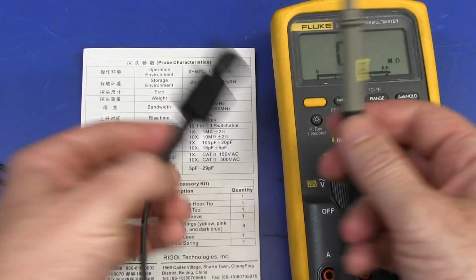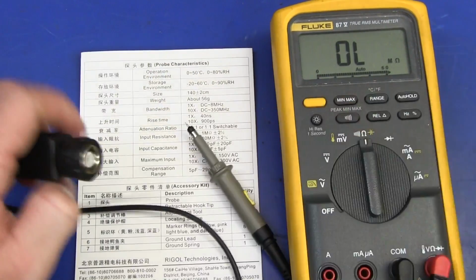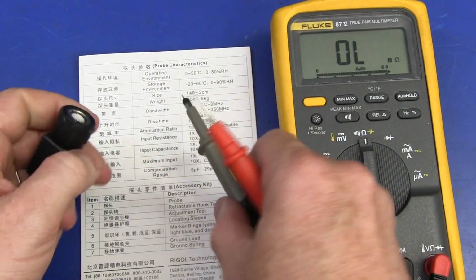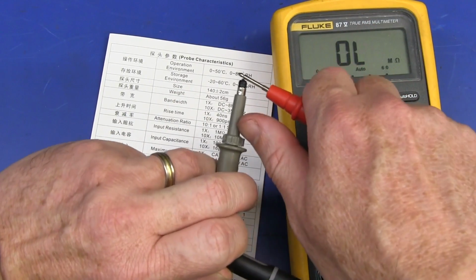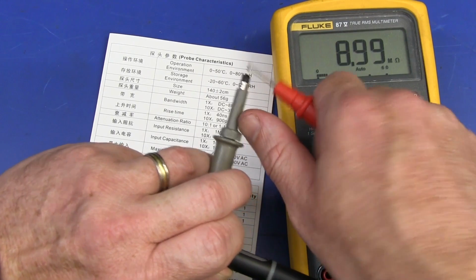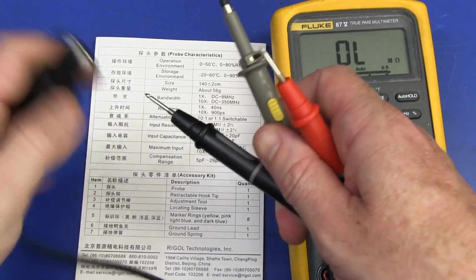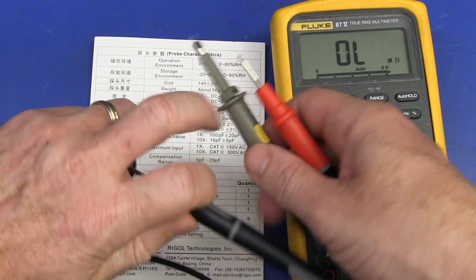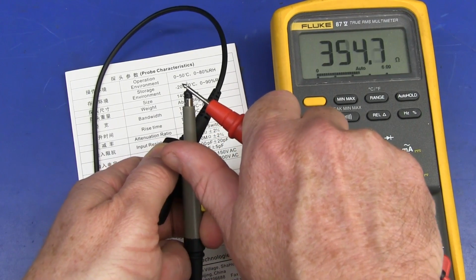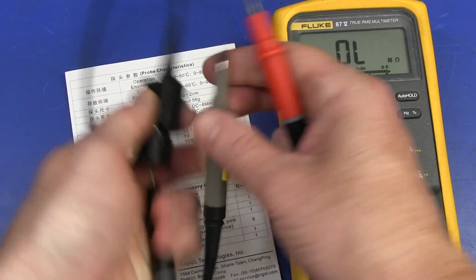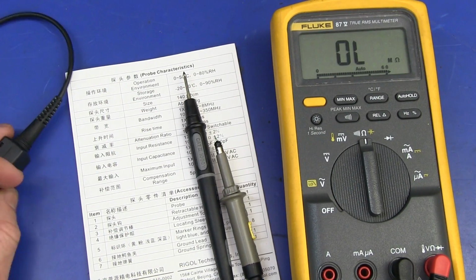But what happens if we measure this scope probe on times 1, by the way? So let's put it on times 10 first, okay? And we should get our 9 meg that we looked at on the board there. There it is, spot on 9 meg, no worries. But we switch it to times 1 and there should be nothing else in there but the switch, right? That's it. You'd expect to get exactly the same as the coax, do we? There we go, 330 odd ohms between the tip and down here. What is doing that? Is there a series resistor in there?